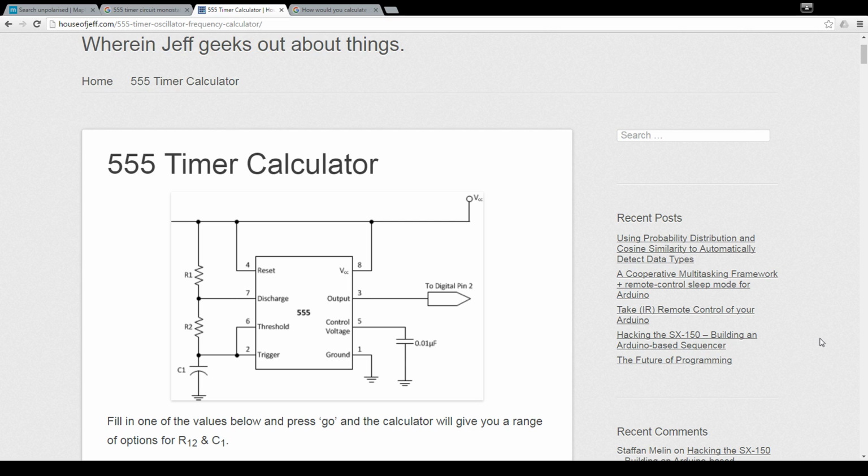Oh, that's what you mean, Goose, about the pulsing LED circuit. Yeah, I know what you mean about doing it using a 555 to make a pulsing LED, but it is an awful lot easier to do it on an Arduino, because you simply write code in which the pulse width modulation goes up, then back down, and then back up, and then back down.